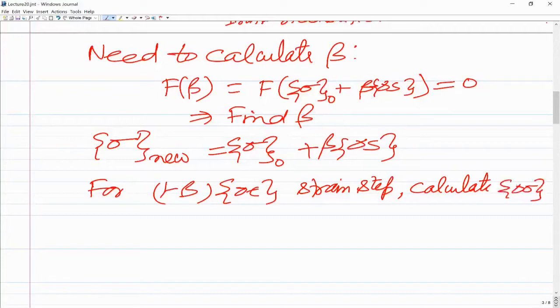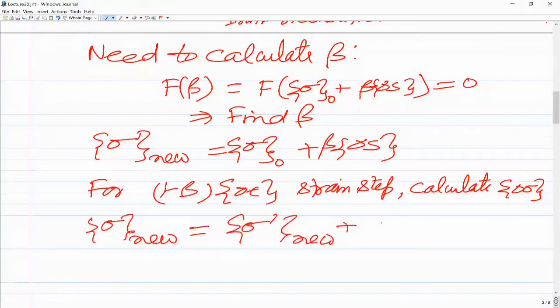That is, you express all the stresses in terms of delta epsilon equivalent P, solve for delta epsilon equivalent P, and then get the incremental stresses. Then the final stress after this particular iteration would be sigma nu equal to sigma dash nu plus delta sigma.